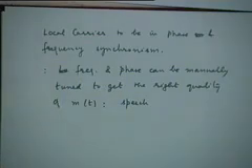You can manually do it in cos omega_c t and multiplying it also. That is what I'm saying. Theoretically it can be done, but that's a much more difficult thing to do than in this case, right? In other words, if you do some analysis, you will find that this is less sensitive to the phase and frequency errors than the other system is, right?